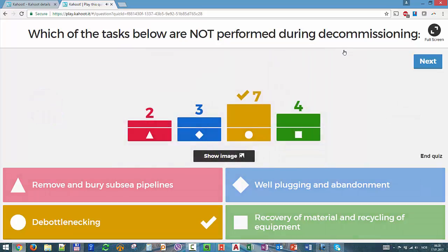That is typically done during operations. Debottlenecking is when you have a limited capacity, for example of gas processing or water processing, and you have reached it. You have bottlenecked facilities. So in debottlenecking, you try to find ways, either reducing the water production or having additional processing units that will help you produce more. The goal is to increase the production of the primary phase, oil or gas.